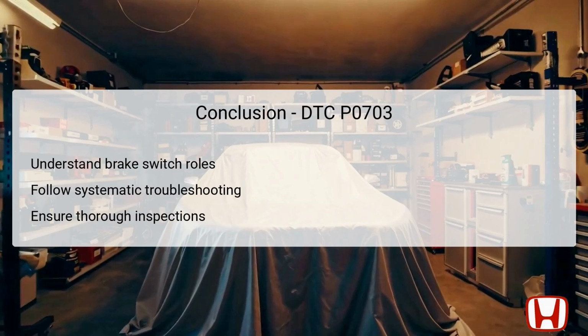In conclusion, understanding the role of the brake pedal position switch is key to effectively diagnosing and resolving issues surrounding DTC P0703 in Honda HR-V models from 2016 to 2022. The troubleshooting steps provided outline a systematic approach, ensuring each component and connection is verified to isolate the issue accurately.